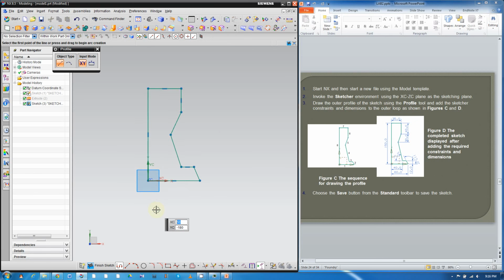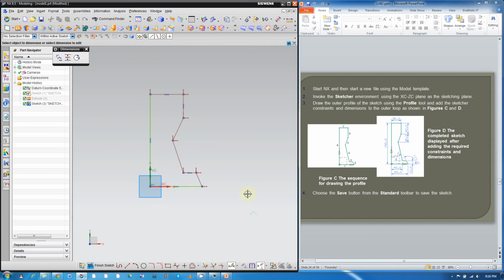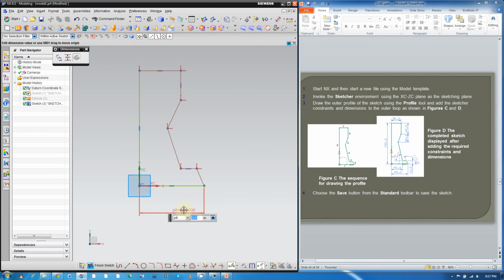Okay, that's pretty quick. And then the next step is we're gonna put in the dimensions. So as you can see, this line and that line, they are already constrained because they start from the sketch origin. Now, you can see the arrow here. That means this point can move along the x axis but not y. This is because of this horizontal constraint. So let's put in 60, and you can see why.